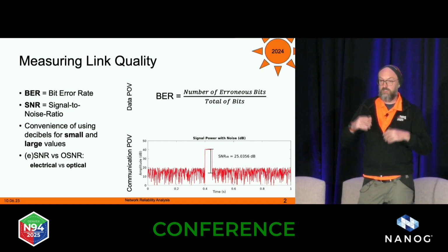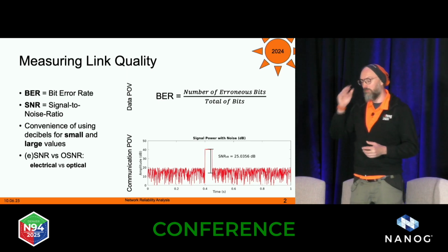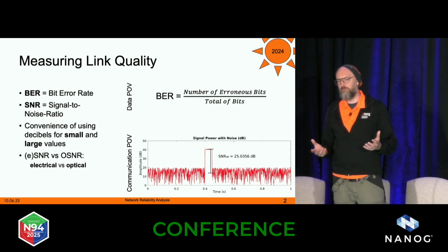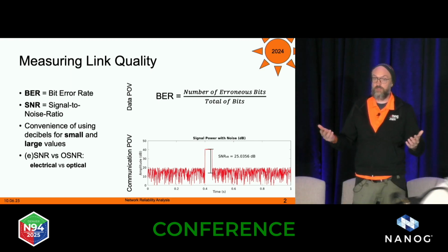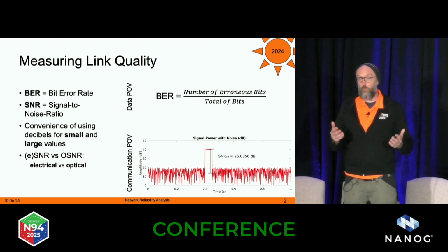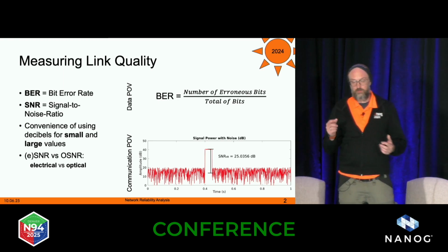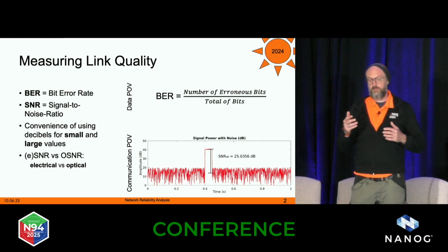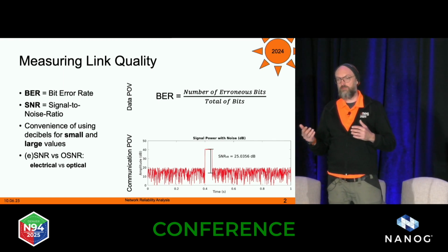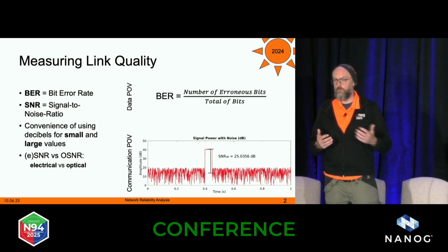then if it's below 20 dB of margin, it's very hard for the receiver to distinguish between the desired signal, actually our zeros and ones, or whether it is noise. So keep that in mind. Both the bit error rate and the signal to noise ratio have a close relationship. You will see that later on.